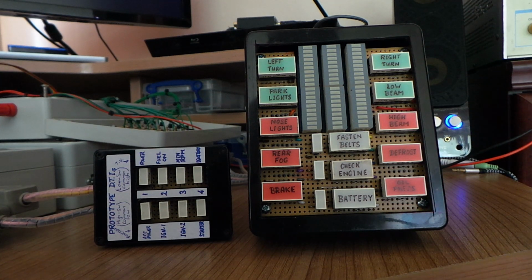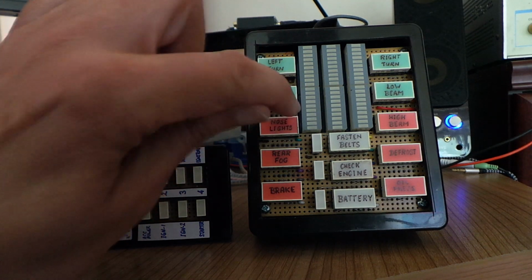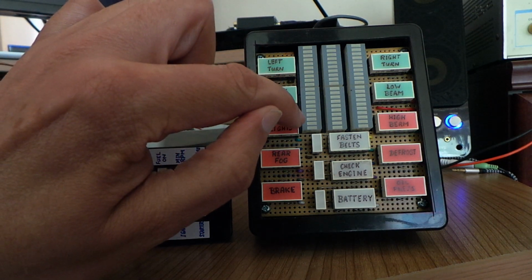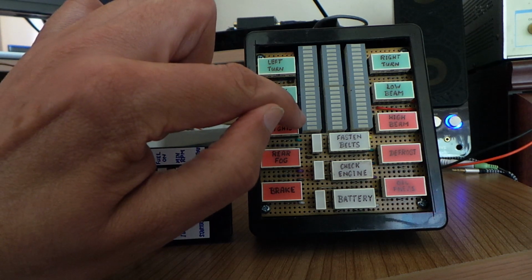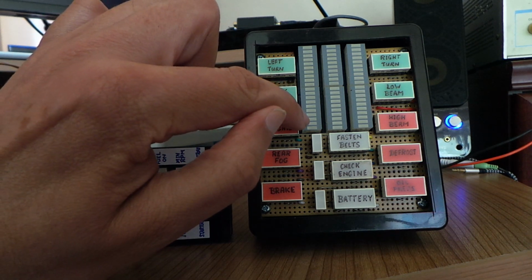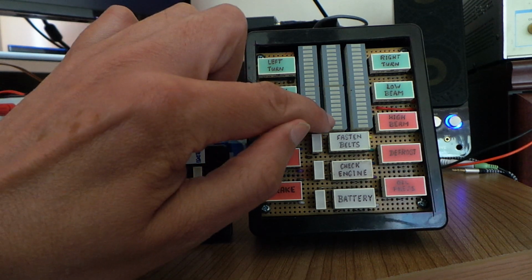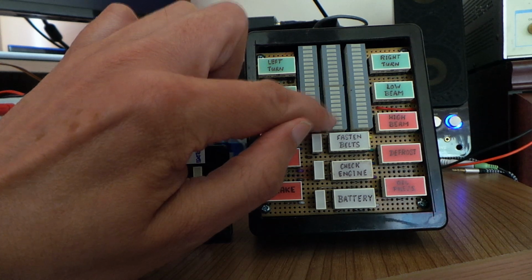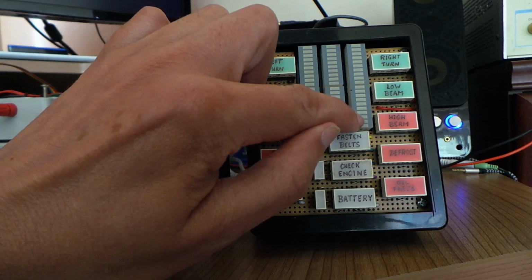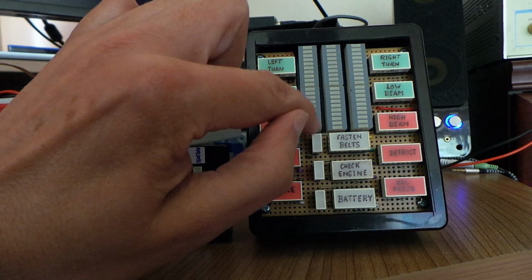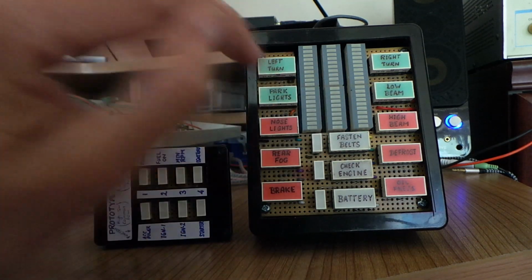as that is the functional mode. And when we first power up, we display the software version number on the voice display in the format of the first digit. So for example, the current version is 23.5, that is built in 2023, month 5. So we'll see the first 2 LEDs illuminate here, the first 3 LEDs illuminate here, and then 5 LEDs indicate on this bar gauge, indicating version 23.5.